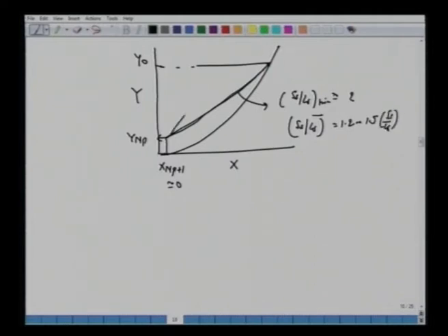So we can construct this to obtain the solid concentration of the first stage, which is x1 here. Then we can reconstruct the number of stages required once we know this operating line and this equilibrium curve here. Again, one has to be careful with the shape of this isotherm.